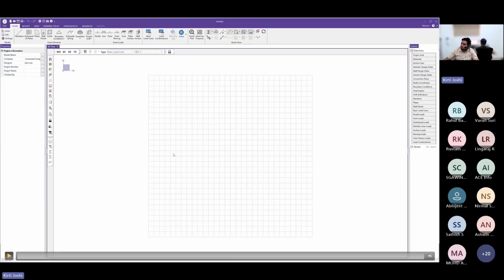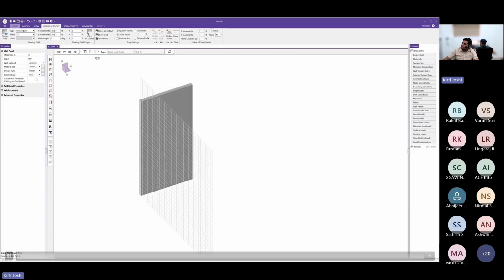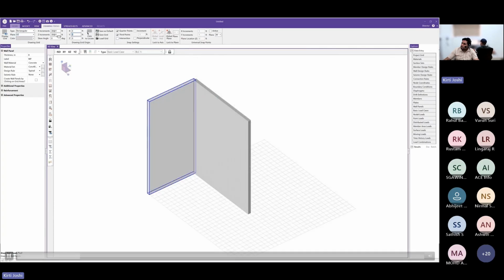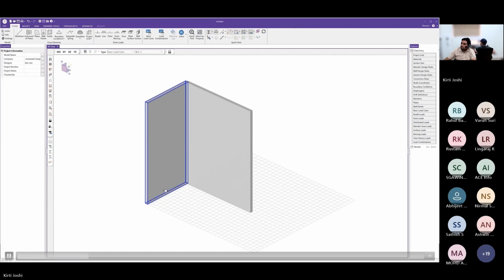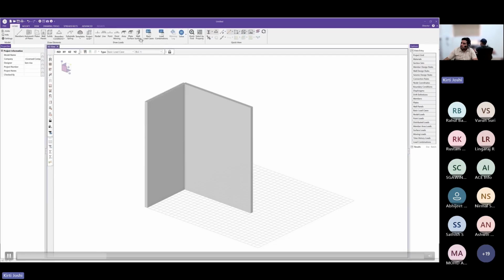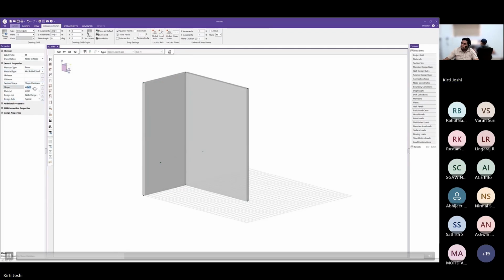This is also a quick video we have created for the modeling. Here we will show a kind of hybrid model, how we can place the concrete wall and how we can assign the staircase. It is a simple stairwell, an L shape. We'll add an L-shape concrete wall here, and we will add a steel stair. Also, you can select the nodes through the tables, or you can select them directly in the model. And you can create your section set.